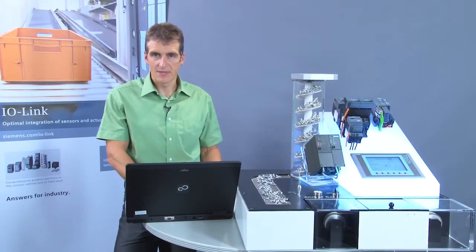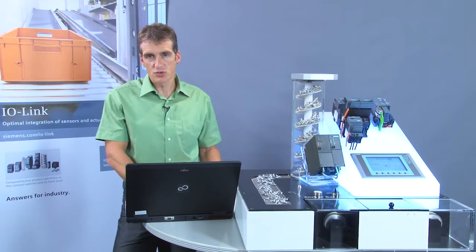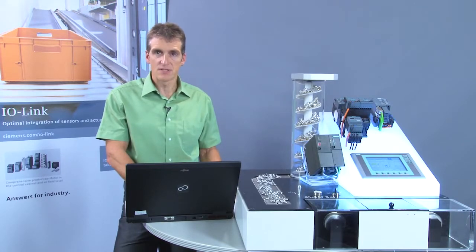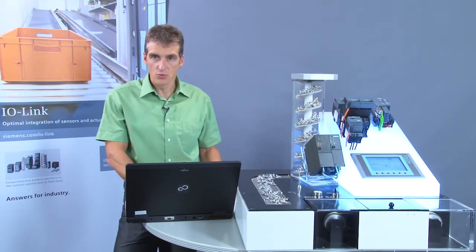I would like to mention that in order to read the parameters of an IO-Link master, the function block's input parameters, IOL index and IOL subindex, must be preset to 0. This is important when an IO-Link master is used on an ET200S system. The function block can be used not only to successfully replace IO-Link devices and IO-Link masters. It can also be used to read additional information and to modify parameters during operation.